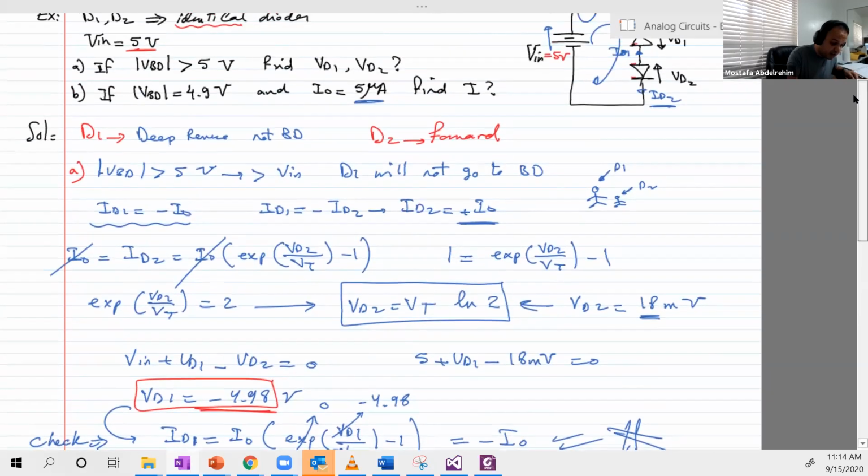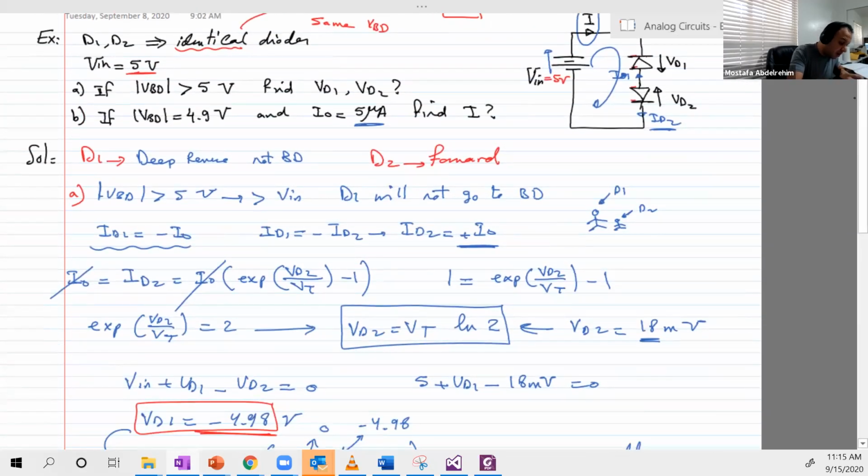Just one quick note on that example in particular before we go, about ID2, which is the current of the forward bias diode. Let's draw very quickly here, going back to this analogy again. So this is VD2, ID2. We know that this voltage should be approximately equal to 0.7 volt, or between 600 or 700 to 800 millivolts. Around 700 millivolts or 0.7 volts.